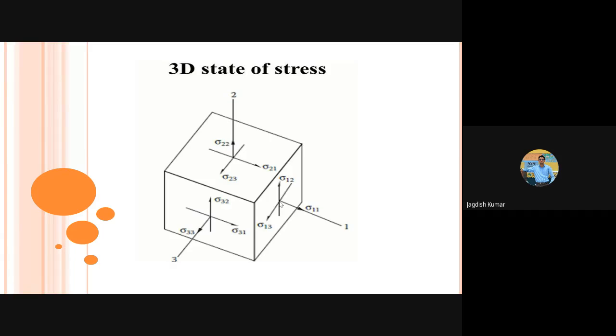Internally, it may be a BCC type crystal, or tetragonal, or hexagonal type of crystal, but over bulk length scales we can cut it externally in a cubic shape, isn't it? So in that sense, suppose this is the X direction, this is the Y direction, this is the Z direction, and 1 2 3 refers to that. Then sigma 1 1 is actually the stress along the first direction.